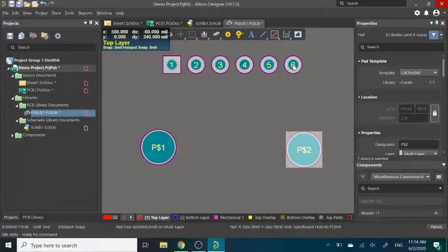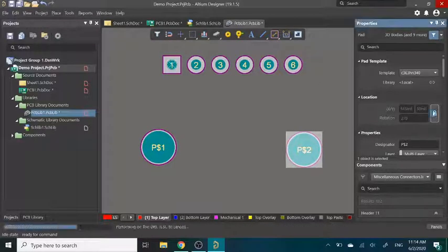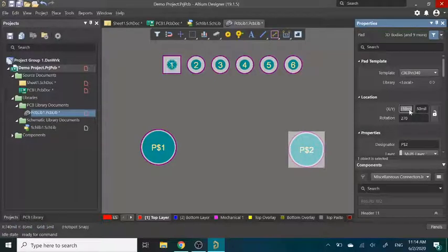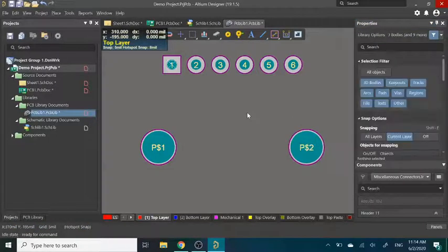We know that this is at 500 mils already, so you can convert it yourself and type in your result, or you can just type in 500 mils plus 1.4 millimeters and it'll do it for you. And this should be negative 8.64 millimeters again. And there we go.